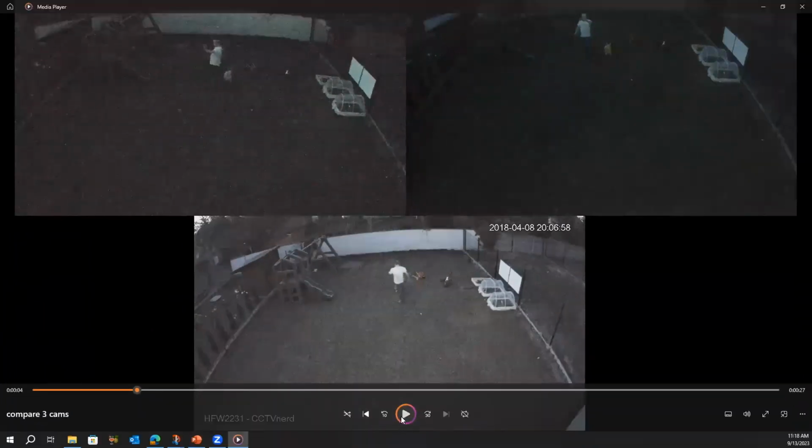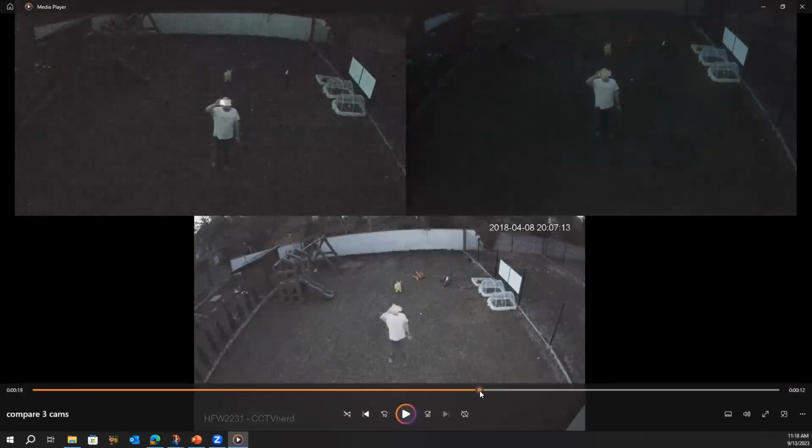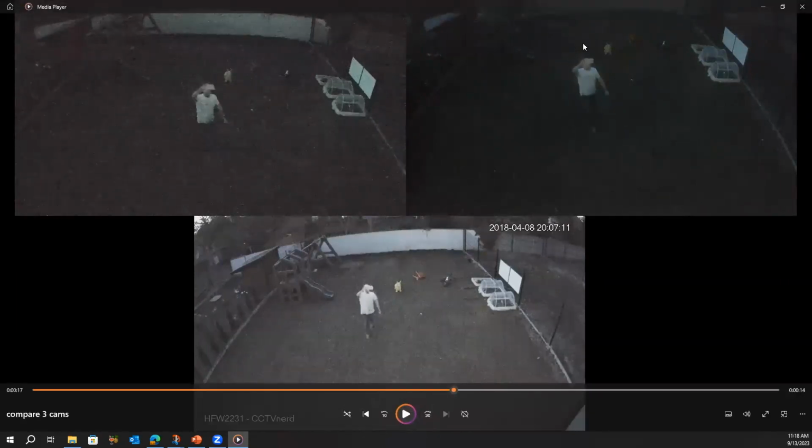Yeah, and I often ask people during the trainings, the exhibitions, and so on, which image do you prefer? Which camera would you choose? To be honest, some people will mark this one because the image is much brighter, right? It's more, let's say, light on this scene. But to be honest, I don't think it's better, because you got lots of motion blur and you don't even see the details on my shirt. On this camera, which is actually Axis, you can see the markings that I have something written on my shirt. So maybe the image is darker, but you have less motion blur.